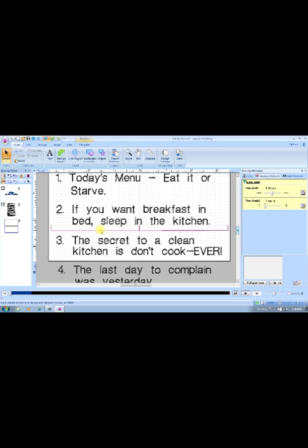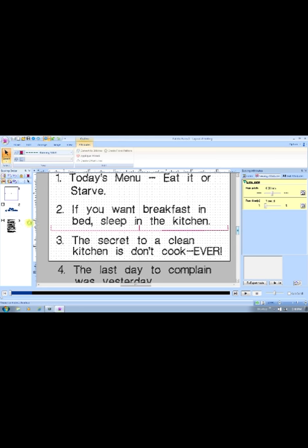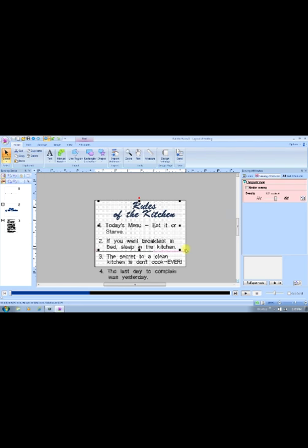So right now I have the one in place for the top, but I want to add another one. First thing I want to do is make sure this stitch is out first. So I'm going to come up here to the sewing order, and I have this red box selected, and I'm going to hit sewing order. So now it makes the reference line that I made last time stitch out first. I'm going to select these items that I've already stitched out. Hit the delete key, remove them.